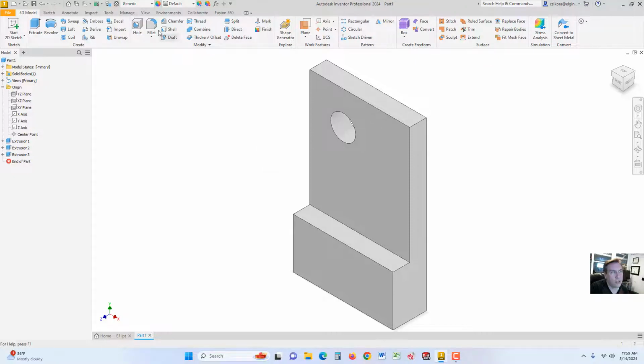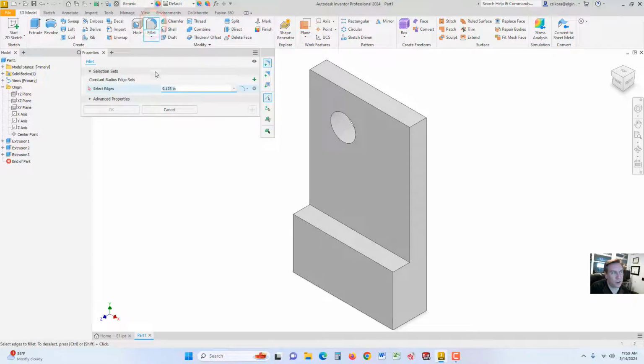All right, so there is the fillet tool. The fillet tool puts a nice radius, like if you were to sand a corner smooth so someone doesn't cut themselves on it. That's what it does. And set your radius here to 1. And go ahead and select this edge right here, and you'll see it puts in the fillet. Okay, it's the preview. You could grab this arrow, drag it in and out, and adjust it if you want. But I'm going to go back to 1.